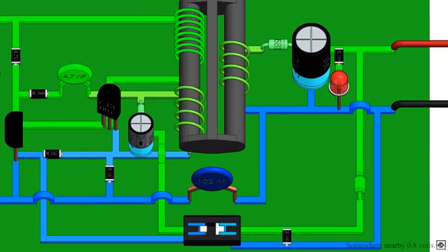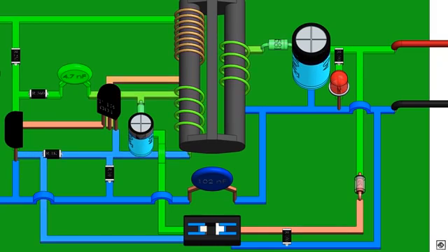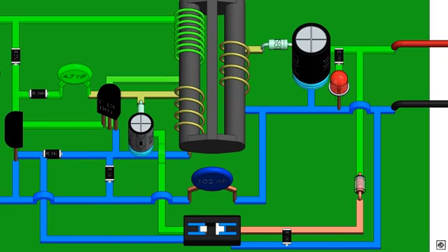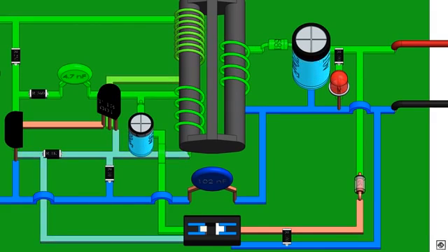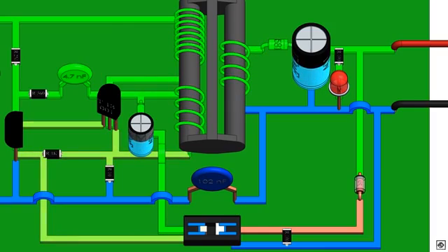When the voltage reaches more than 5 volts, this turns on the LED of the optocoupler. The light of the LED turns on the phototransistor of the optocoupler, allowing the current to flow to the transistor T2. This turns on the transistor T2, shunting the first and stopping the flow of current in the primary winding. Also, the voltage on the secondary side of the transformer drops below 5 volts, turning off the Zener diode and optocoupler, and the circuit continues to run normally.